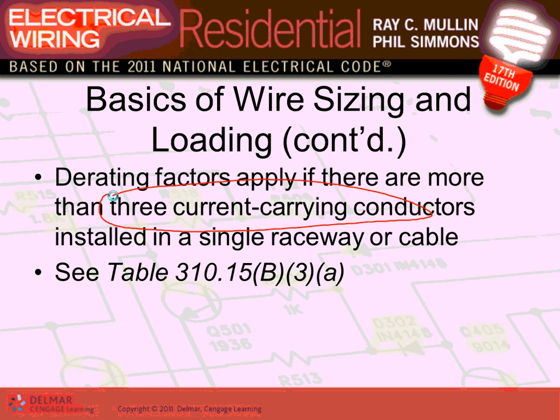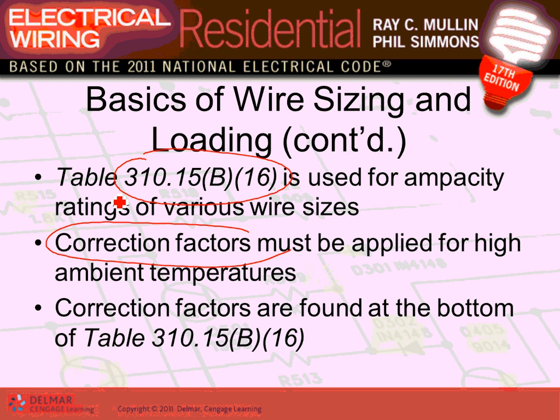So some of you, Derek and probably Matthew, did not do that one. So Table 310.15(B)(16), guys, will give you the ampacity of these conductors. For example, number 12 can give me 30 amps under 90 degrees Celsius. Under 90 degrees Celsius, number 12 can get you 30 amps.